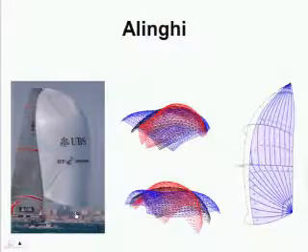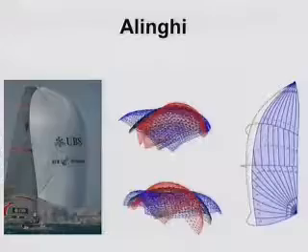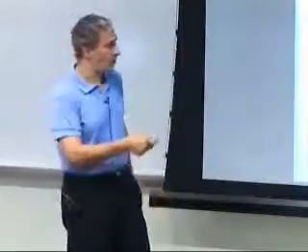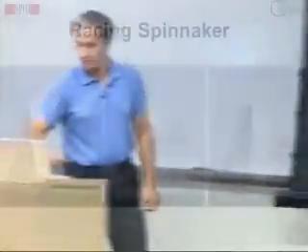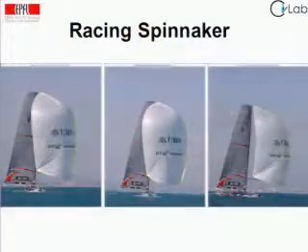And the system we delivered to the sailing team is based on that idea. We have a model of the spinnaker in its rest shape, which is the model that was used by the sail maker to actually cut the panels of which the thing is made. Which means we could compute the deformation modes and fit it to our videos.